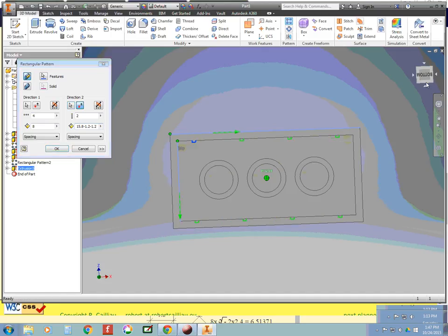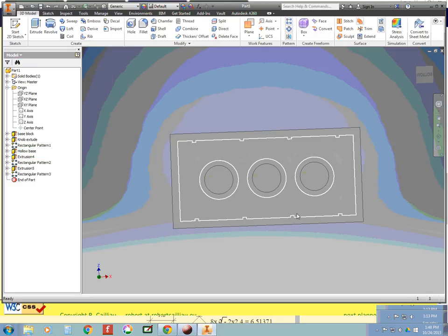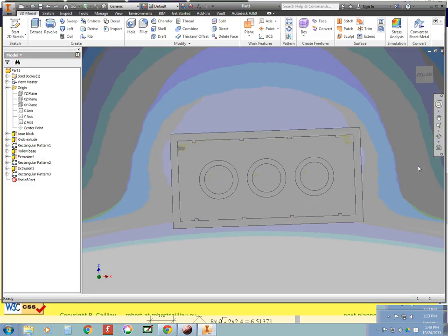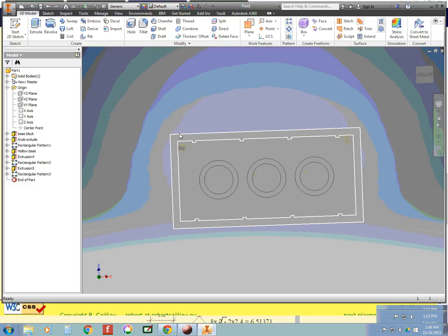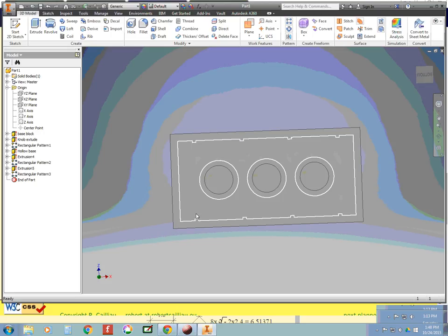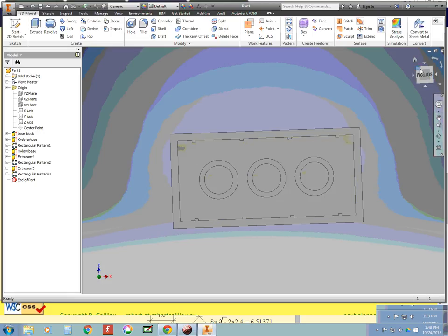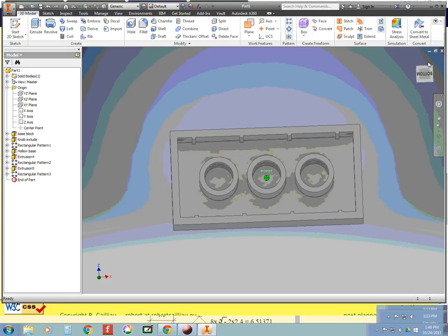And if you notice, it's still on the outside. We also need to subtract the thickness of that extruded feature, and that was minus 0.3. So we've got to go back in here, minus 0.3, and should be good. Let's see what we get. Go ahead and click OK, and we have them. So once again, we did the distance across here, subtracted the wall thicknesses, and then the thickness of that extruded piece itself. We rotate, we can see those pretty well.